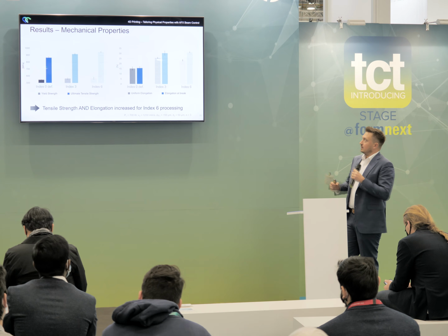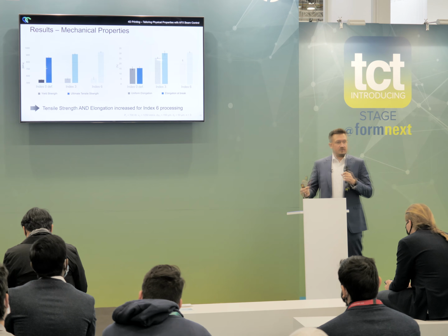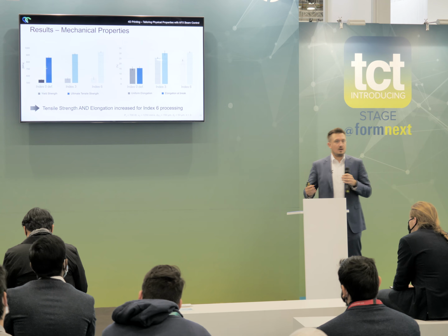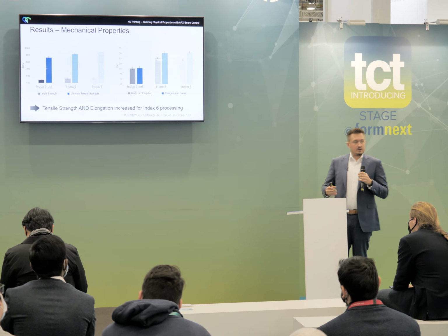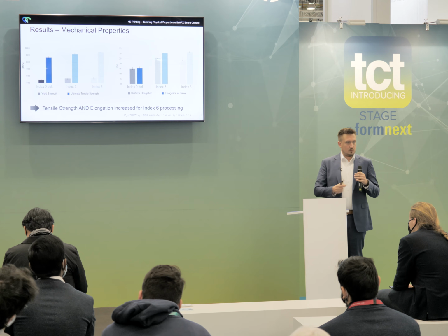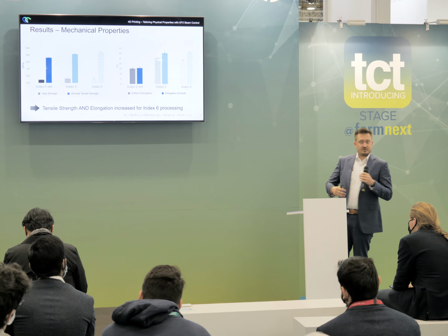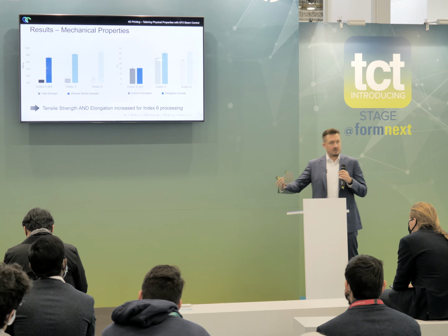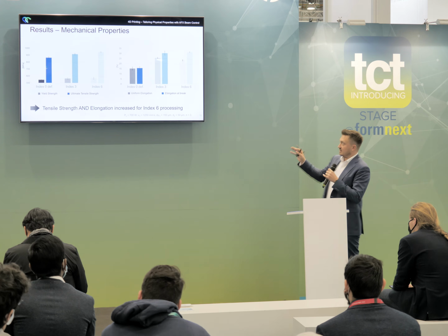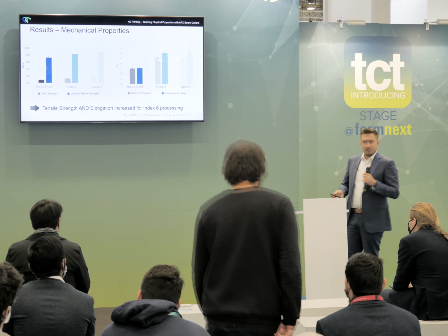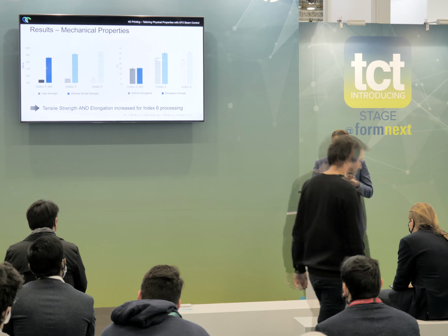And also interesting is that we achieve as-built mechanical properties with the ring mode intensity distribution that we are used to from the standard single mode process with significantly smaller spots. But this allows us then to have the same properties at significantly greater melting rates of, in that case, more than 9 cubic millimeters per second. But the question remains, why does it happen?